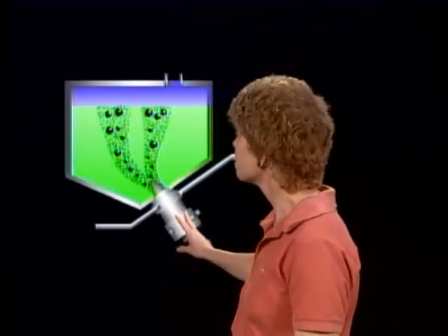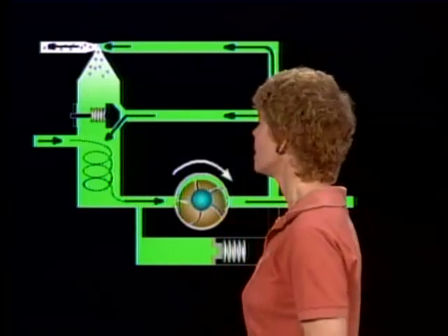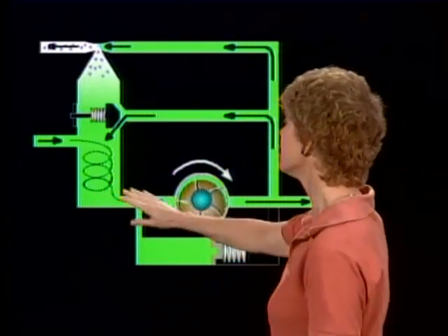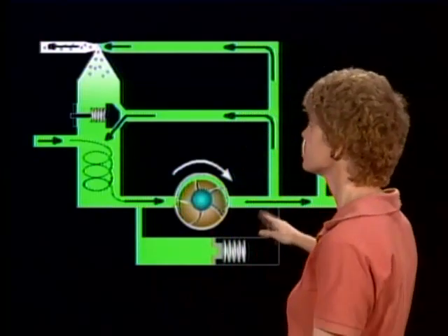A centrifugal type pump like this is not a positive displacement pump. The primary fuel pump on the engine does tend to be a positive displacement fuel pump, and a positive displacement fuel pump has to have a fuel pressure relief valve. It's required by the FAA regulations because it's always putting out the same amount of fuel through the pump, and the engine is not always able or ready to accept that much fuel pressure.